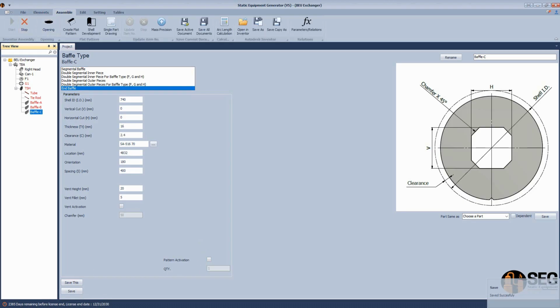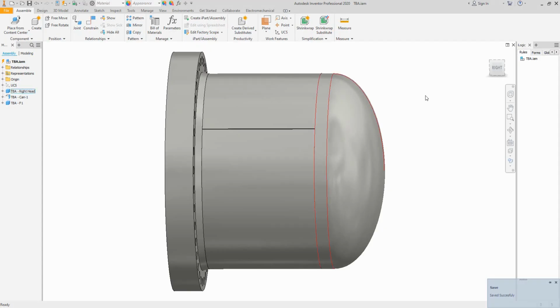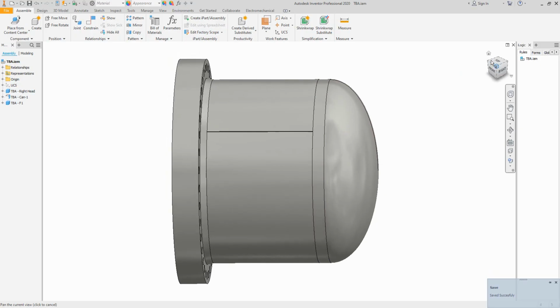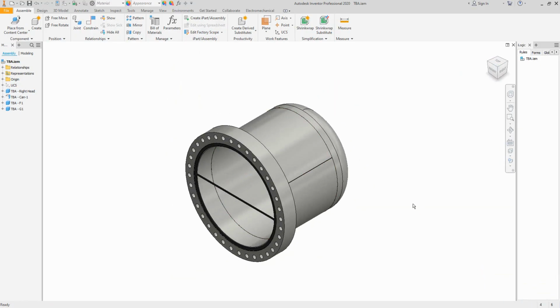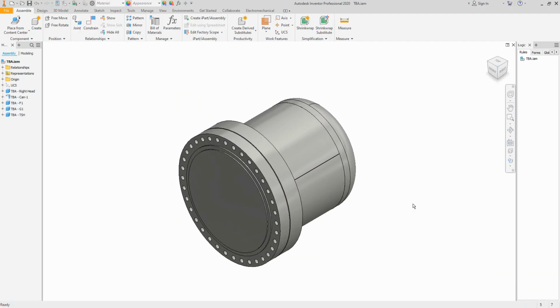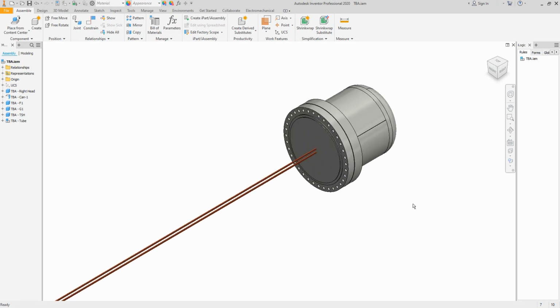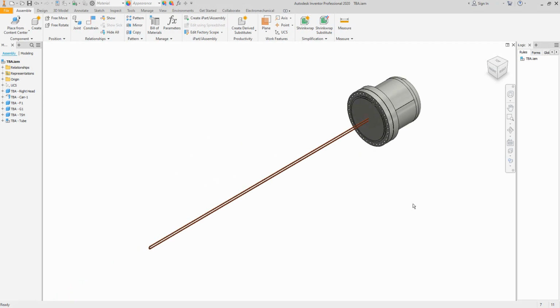Now let's create the assembly. So the first part will be generated, which is the gasketed pass partition, which is that one. After that, the tube sheet, and finally the attachments for this tube sheet, like bended tube, the first bended tube, the tie rod, and the 3 baffles.